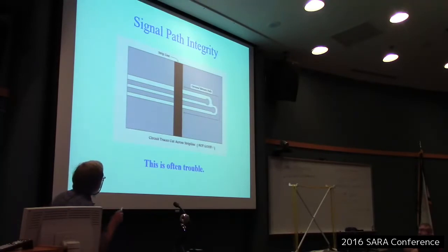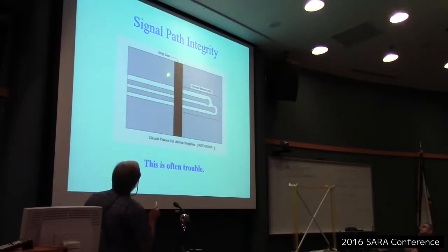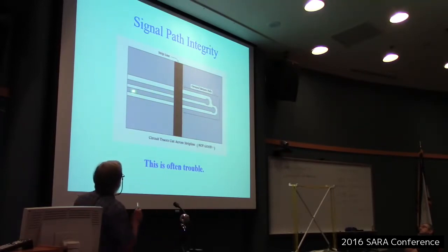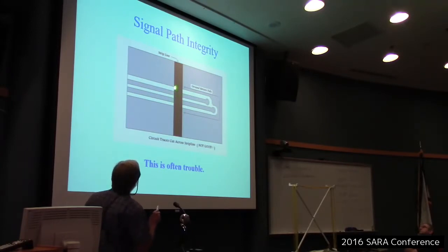Now, this was another microstrip thing I ran into. It's quite interesting. This is looking from the top, and the gray is the grounded area. Somebody needed to get some traces across there, so they run right under the microstrip. Well, this is a serious violation: the signal is going along this path, whereas the ground has to go out there and back there, so the ground currents aren't flowing the same path.